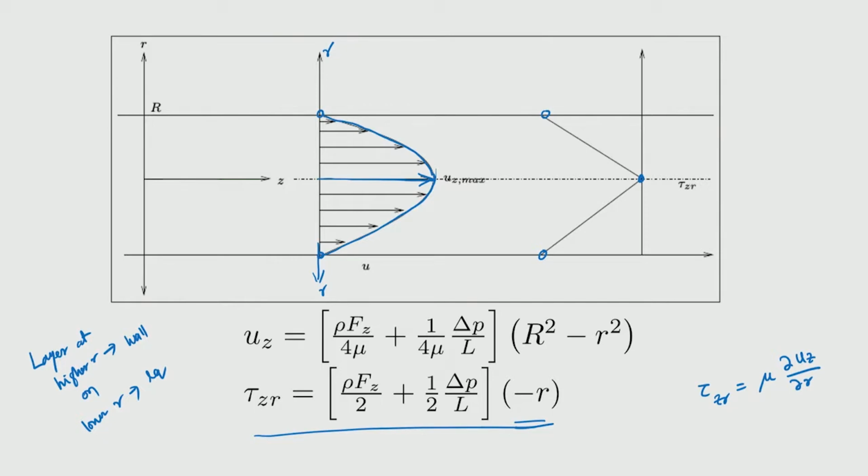If it is actually along the positive z direction, then the stress is positive, but actually as we can see here, it is actually trying to stop the velocity from taking a magnitude at the wall, and therefore, the stress is actually acted upon in this direction, that is opposite to the positive z, that is in the negative z. So, therefore, the stress has to be negative. So, that is how the convention actually is also coming out neatly even in the cylindrical coordinate system from what we have written earlier. So, mathematically what is shown, if you plot, it actually also makes sense with respect to the functional form that we have given.